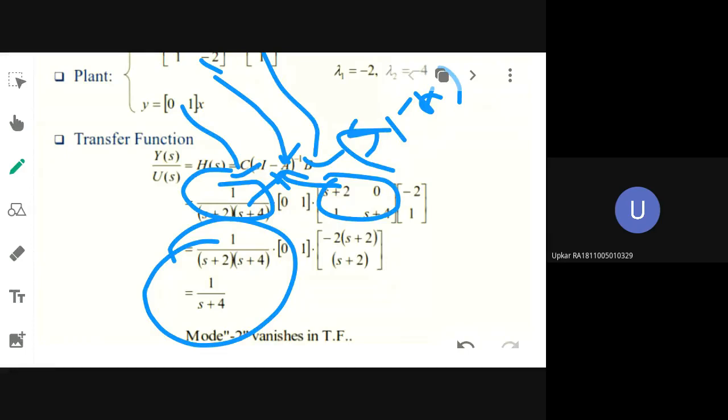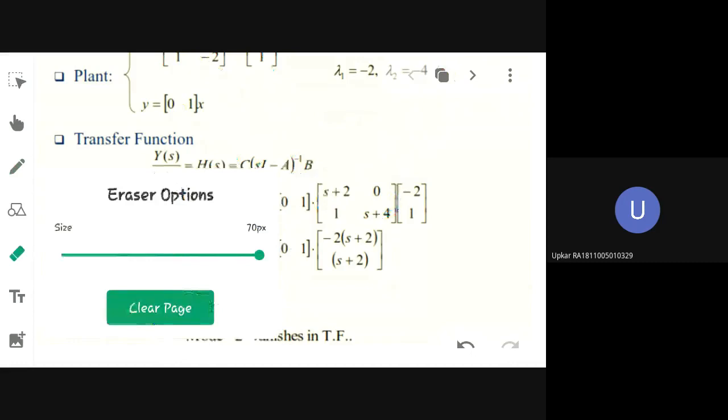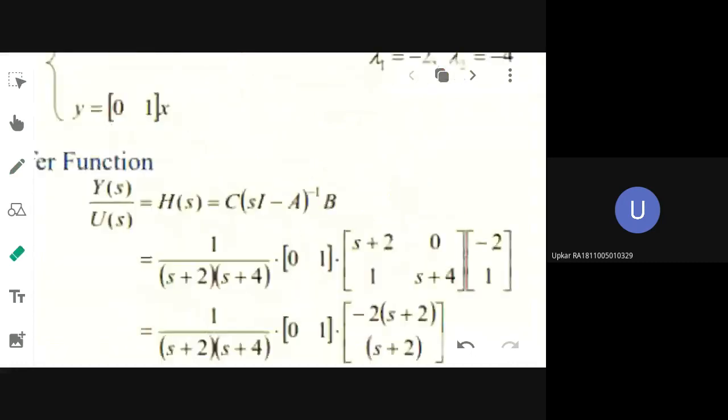So you understood how to convert a state space model to a transfer function. What is the formula again, one final time? Do remember this formula again and again. I am telling you, C into (sI minus A) inverse B. Very important question, maybe asked in your future competitive exams also, like civil service or IAS exam. Very important formula: C into (sI minus A) inverse and B. All the product you have to take and this will give you the transfer function. The reverse is also possible, and the reverse is already easy. Just pick the state variables and form the A, B, C, D state space model.